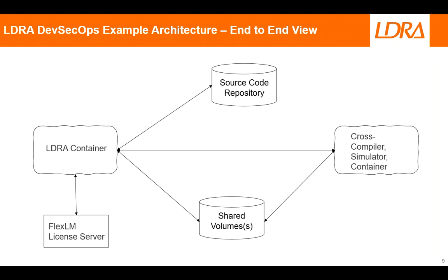When using embedded development, ensuring the cross-compiler location and targets are all accessible by the container is key in order to execute the test cases on the targets when performing dynamic analysis or regressing the unit testing. The source code repository will also need to be reachable from the compiler prior to setup.